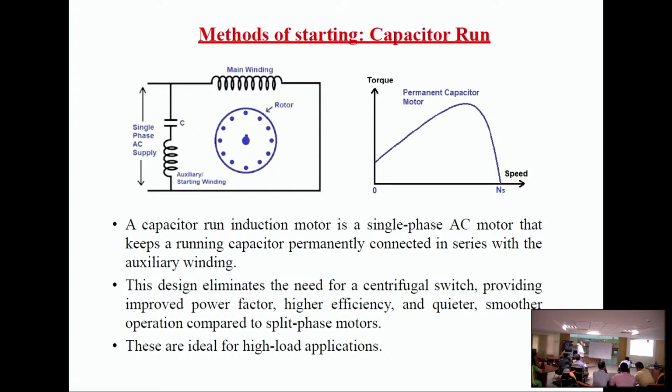So capacitor run induction motor is a single phase AC motor that keeps the running capacitor permanently connected in series. So this design eliminates the need for a centrifugal switch, and so with the permanent capacitor, the power factor will be improved.